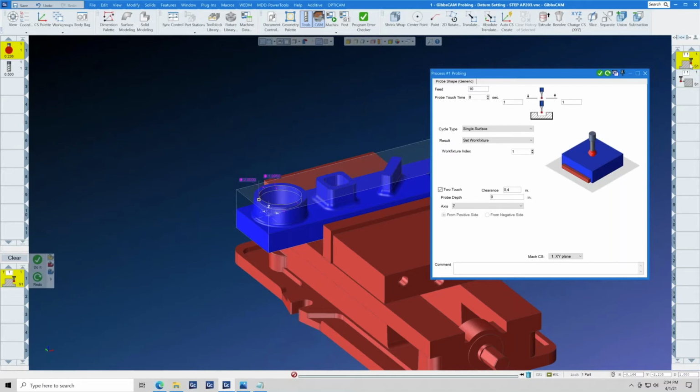Next, we want to help you reduce scrap, rework, and concessions to your customers. In this webinar, we will talk about cutter parameter update. In other words, we're going to employ cut, measure, cut technology, having the probe adjust our wear comps for us to get the part as close to print tolerance as possible.